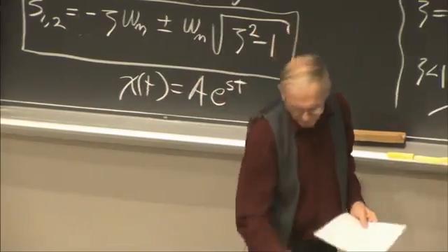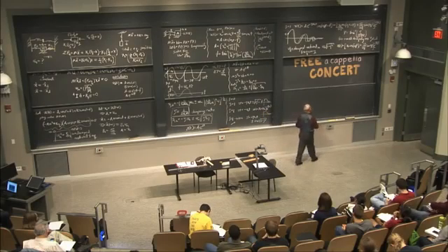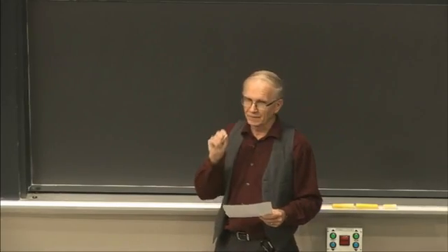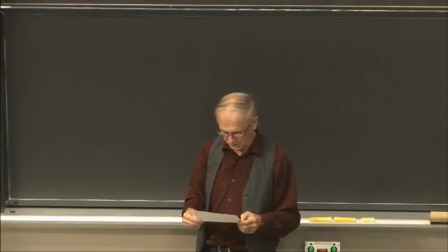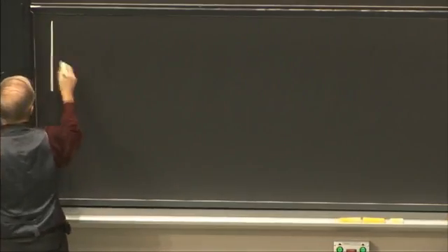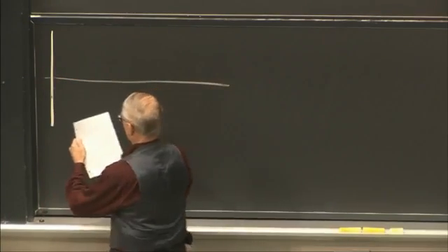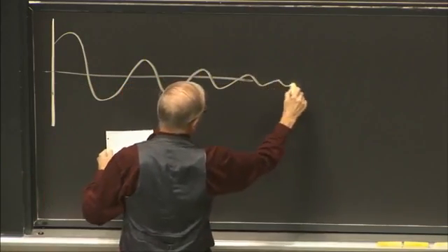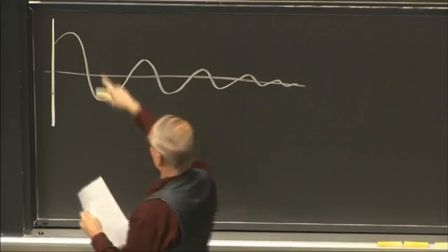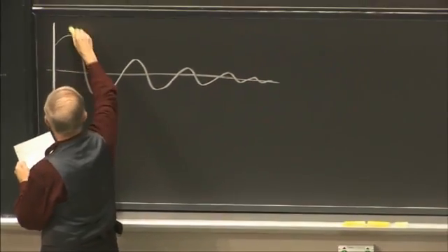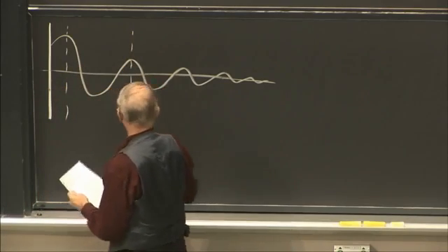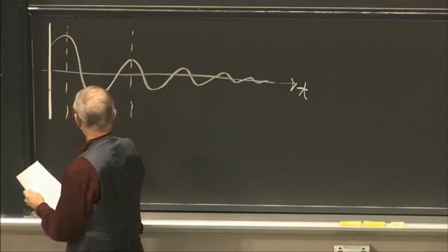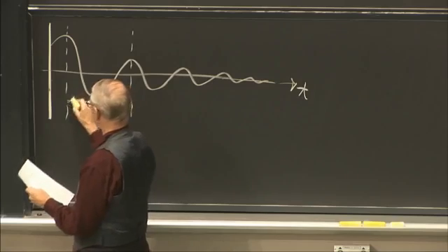Okay, so I'm trying to impress on you that damping doesn't cause much of a change in systems that actually vibrate. If you can observe the vibration, damping cannot possibly account for a very large shift in frequency. Okay, what's the motion look like? Let's move on a little bit here. So that's what this solution looks like. We know it depends on initial conditions. The distance from here to here, we'll make this a time axis. This is one period. So this is tau d, the damped period of vibration.